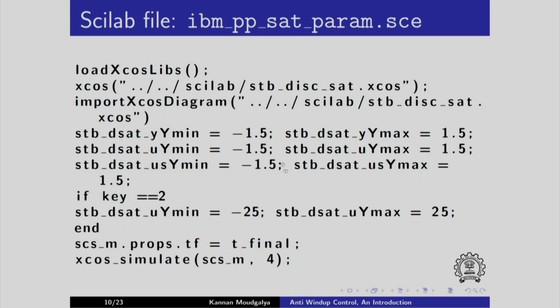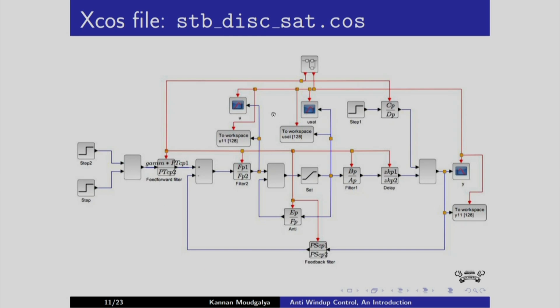After simulating, this file is to be executed to set the initial values for this Xcos code, which is stb_disk_sat.xcos, and you have to load it from the directory in which this resides. And here is that Xcos file's screenshot.